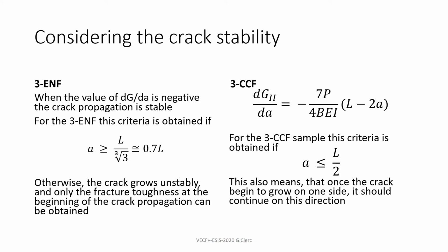Now let's discuss shortly the crack stability for our two samples. For the 3ENF sample, we want to know if the crack will propagate in a stable manner or not. To investigate this, we have to see if the derivative of the energy release rate over an increment of the crack length is negative. This basically means that when the crack is growing, it will make some energy free, and